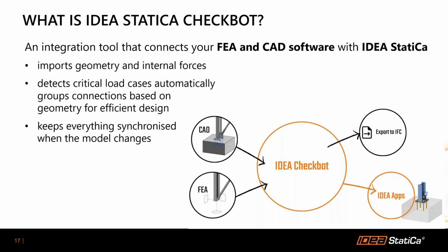You can import geometry and internal forces, especially from the FEA. It detects the critical load cases automatically, groups connections based on geometry for efficient design, and keeps everything synchronized, mainly the loads, when the model changes.